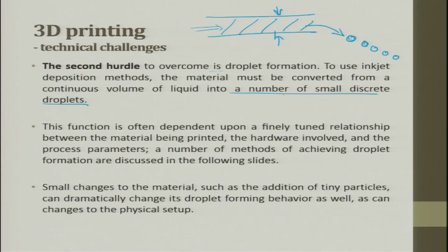And when you burn it or do post processing, when you anneal it, a defect starts from that process. So here this is a big challenge. You have to understand the fluid flow through micro channels and getting dispersed into small droplets. The droplet size plays a very important role. If the droplet size is large, then unnecessarily a lot of binder will be used. If the droplet size is small, it has to be synchronized with the feed rate. If that is not done, it is prone to defects.